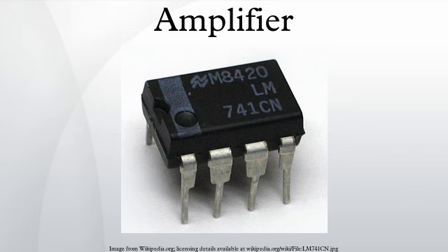They provide the majority of the current amplification and directly drive the load, connected via DC blocking capacitor C2. The diodes D1 and D2 provide a small amount of constant voltage bias for the output pair, just biasing them into the conducting state so that crossover distortion is minimized. That is, the diodes push the output stage firmly into Class AB mode.